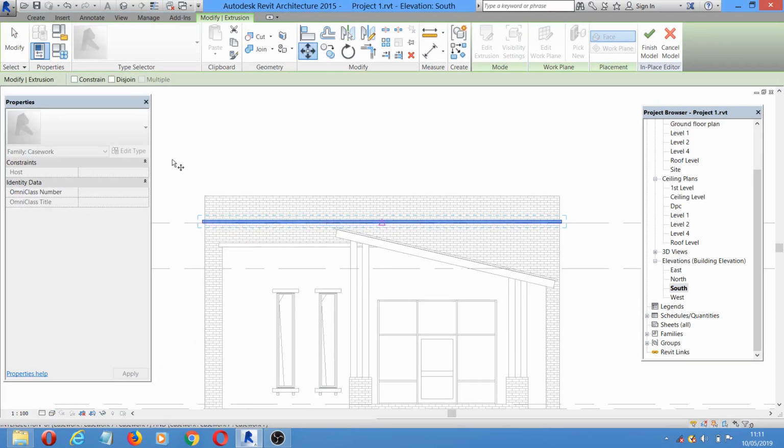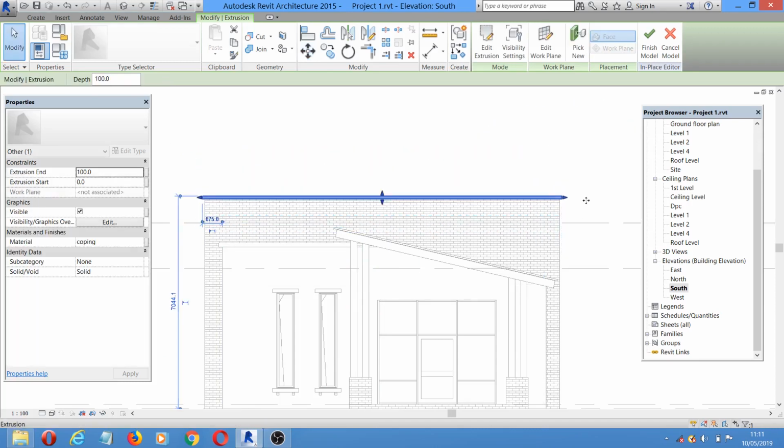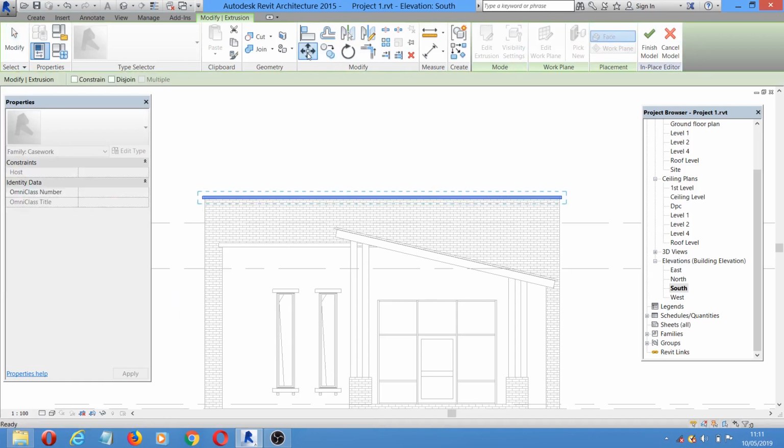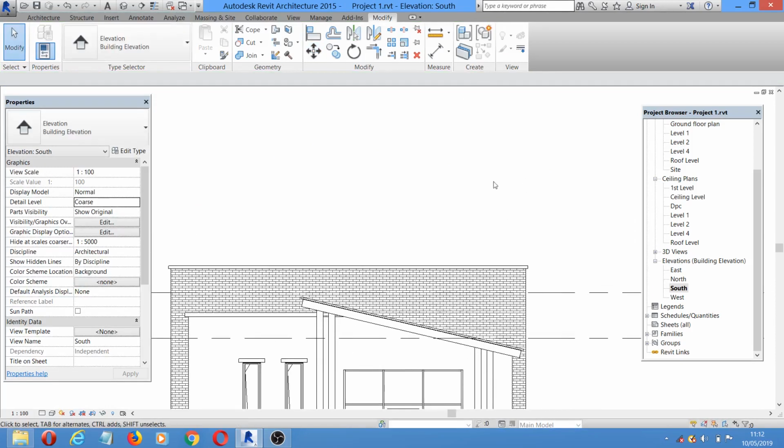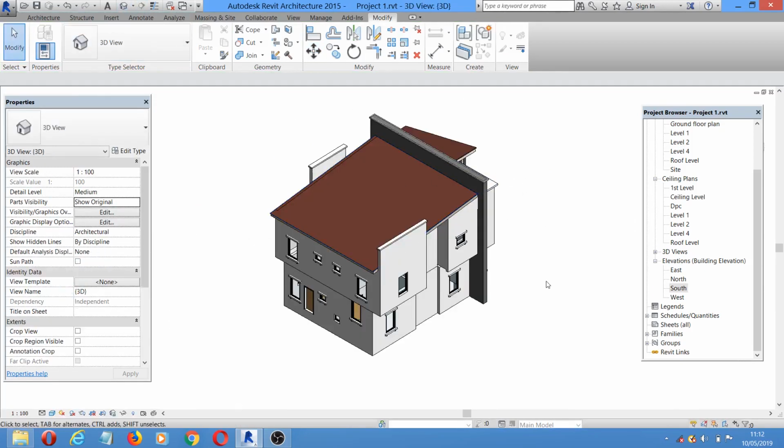Now we can move it up, and in moving it up, if you move it now, you will see it is moving. Okay, but sometimes if it does not move, then you have to either check the constraint or you check on the disjoint. If it's not moving, if it's constrained, then you uncheck the constraint and check the disjoint so that you can move it freely. This time around it has moved because of the way we used it before.